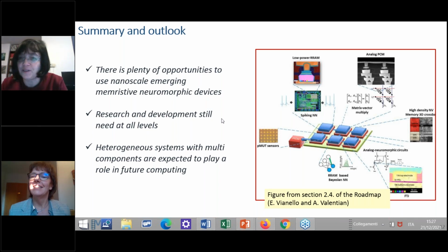Thank you for the question. It's a very important question. I would say that for filamentary redox devices, the array integration has been demonstrated and is quite good. I think the only better technology is phase change memory. For emerging technology, it's true that the array demonstration still has to be done. I think, yes, there is room for improvement, but filamentary resistive RAM are already there, and many chips have been demonstrated with comparable results to PCM or ferroelectric memories.